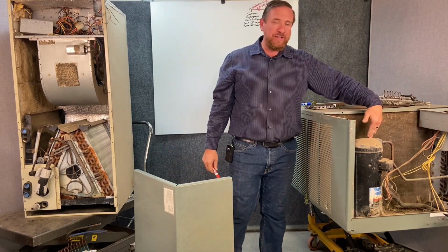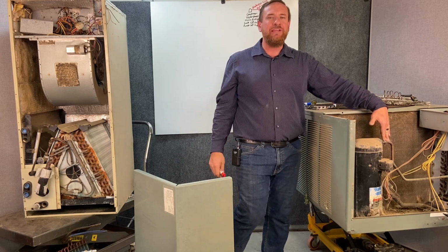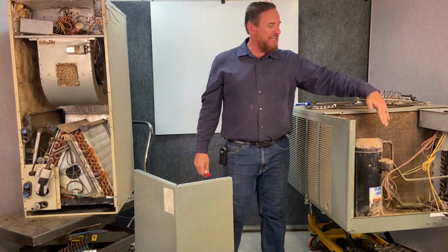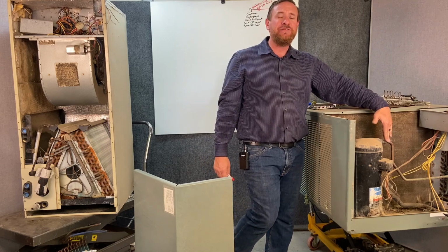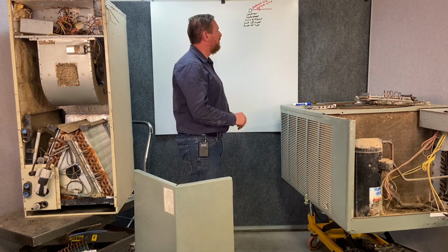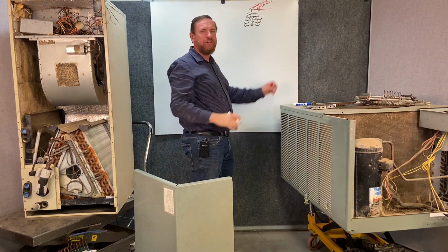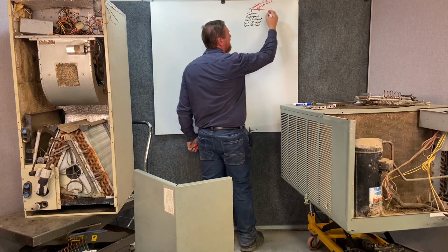And it's vapor coming into the compressor, vapor coming out. Vapor and gas can be interchanged many times, but that hot gas, or high temperature, high pressure superheated vapor, is very hot right here. What we're going to do is send that hot vapor to our next component. And we're going to add more words into this. We're going to be adding to this coil, so it's not done.